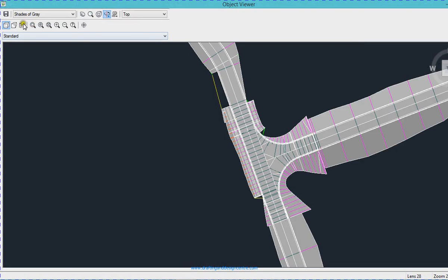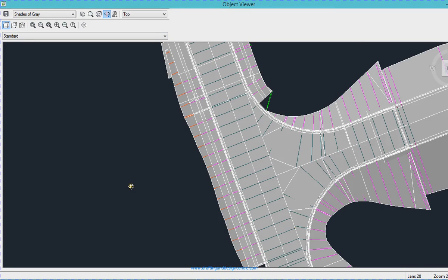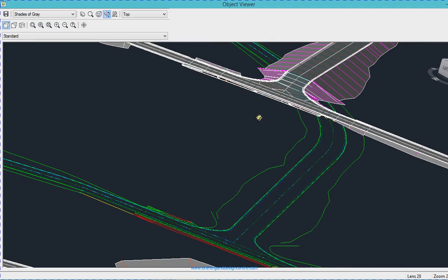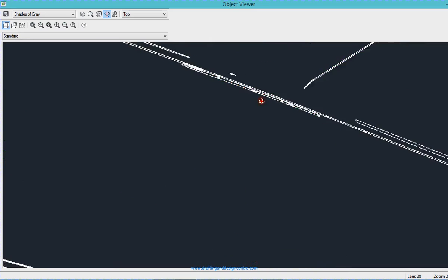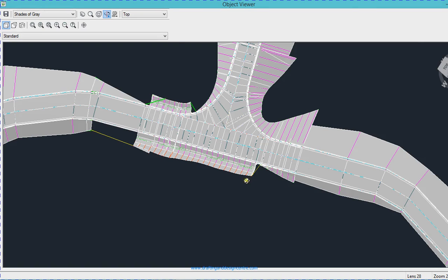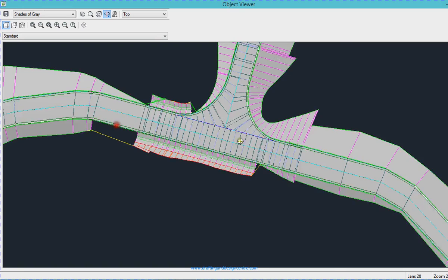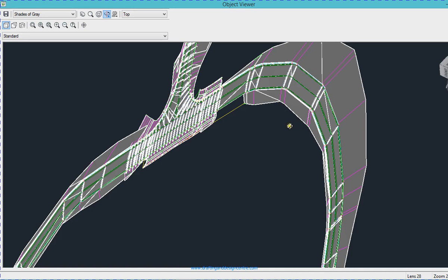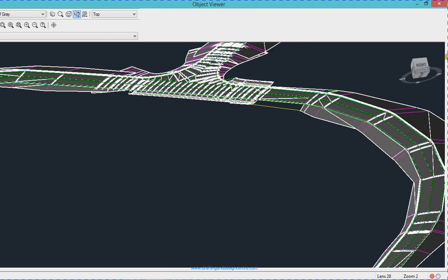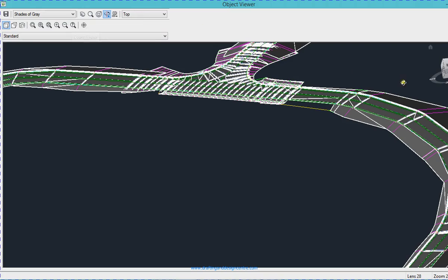And you can see how nicely they have come together, and you can see this in a 3D view by aligning the alignments, how best you can fit the geometry and create an intersection for primary and secondary road. And we then changed the parameters as we required based on the predefined subassembly of primary and secondary road. And now we are just viewing in 3D how the coordination looks from a construction objective point of view, and later on it comes to matching the standard criteria and everything.